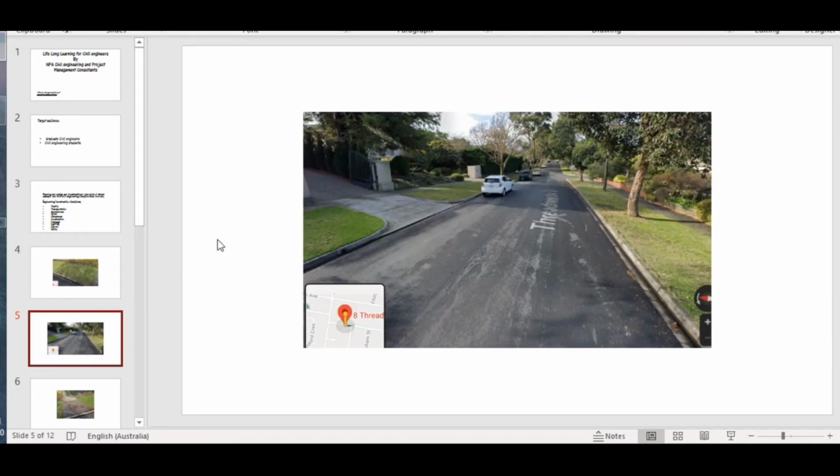Now we can talk about transportation. As you can see on the road, all the way is straight. There is a bit of a sag here, a bit of a crest here. This is draining this way. It may involve connecting this road. Then you might be involved in designing the center line, making sure how exactly the road can connect at the center, at what grade, and how visibility can be influenced when you are driving the car. Can you see and perceive the entire movement, and when you turn, can you see incoming and oncoming traffic to reduce the conflict, and perceive that?